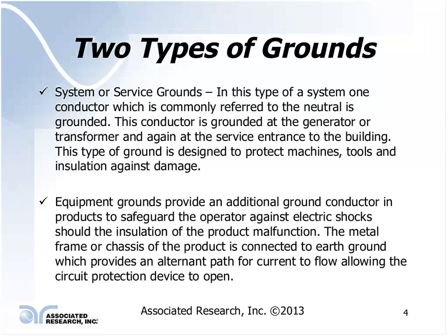It also provides another path for the electrical current to flow, a low impedance path that should provide protection to the operator by allowing the circuit protection, fuse or circuit breakers, either within the product or within the system, to open up, shutting off power to the device that has a short circuit. So grounds are very important.